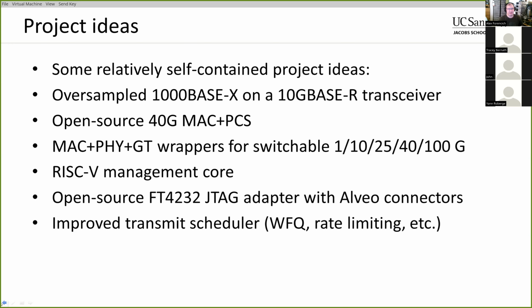Right. Well, the other thing is that you can always drop down more cores for application-level stuff. By keeping the management core separate from all of that, it should keep things more straightforward. Like I said, if you wanted to use a Zynq, you certainly could, but it might make it harder to use a Zynq for application stuff. If we have a dedicated management core of some sort, then you can do whatever you want with the Zynq core. Yeah, I'm a Xilinx guy, so I would have gone for a MicroBlaze or a PicoBlaze if we're just bit-banging registers.